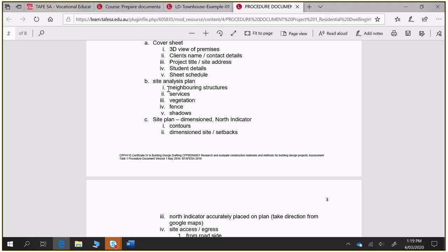But we don't so much need any measurements of anything too accurate of the surrounding. Because there's a house here, the road's there, there's a dividing traffic island, and just general terms of everything outside of that site. Yes, exactly. So all you have to do is paint that picture to convey the information that is important. Because we're not measuring off other houses and things like that, we don't need to dimension anything. And where you don't need to dimension anything, you shouldn't. Because you never want to lock yourself into information which you don't have to provide, or information which you might not be able to back up.